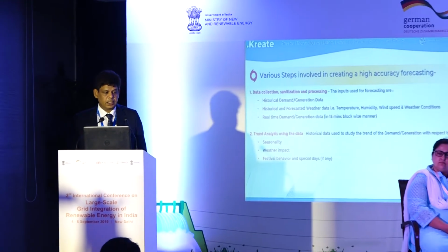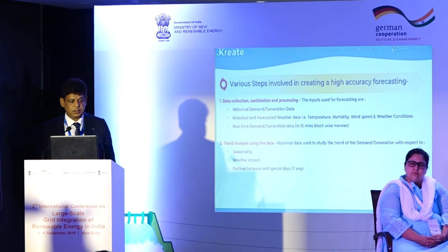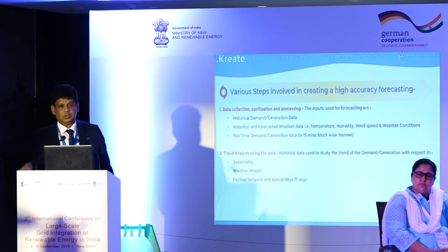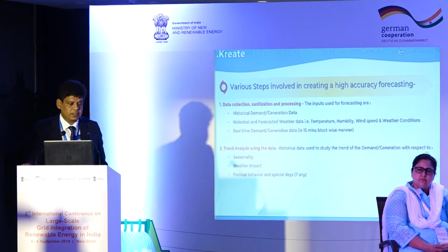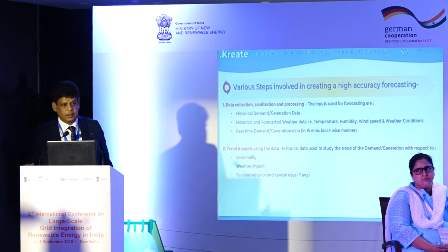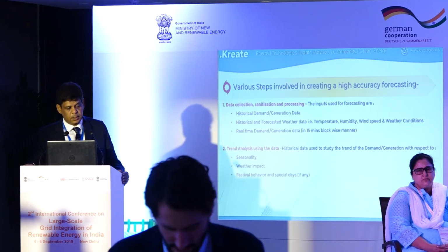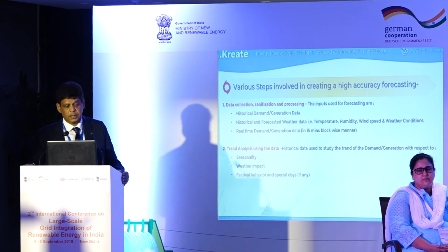So the first step is getting the historical data. If it is demand, then the demand data. If it's for generation, then the generation data. Then you also need to collect the historical weather data because that's another critical factor. That's where we faced maximum challenges, because weather data as of today is probably available, but historical weather data for a particular site is a multiple challenge, especially for a country of the size of India, and some of the states which are very big, it is very difficult to get weather data for multiple lat-longs. So this is another area which we collect very diligently.